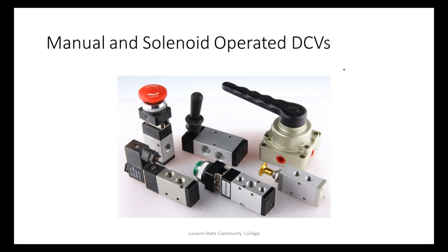So these are some valves. We can see them over there. Ours don't use big solenoids, ours use very small solenoids, and ours are usually pilot operated. We're going to get into this. Pilot operated means you have a little tiny valve that your solenoid opens up, and then it uses the pressure to move the spool.